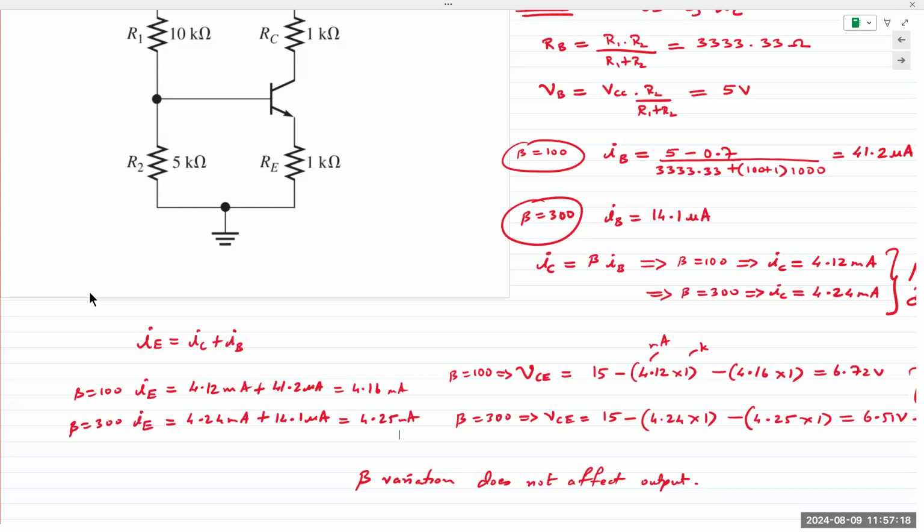You obtain equations for your input base current. Your base current is the input, so you obtain expressions for IB. Then you obtain expressions for VCE and IC at the output. Well, IC is simply beta times IB, so you don't have to do any derivation for that. But we do need to derive an expression for VCE, and we simply obtain that by applying KVL.